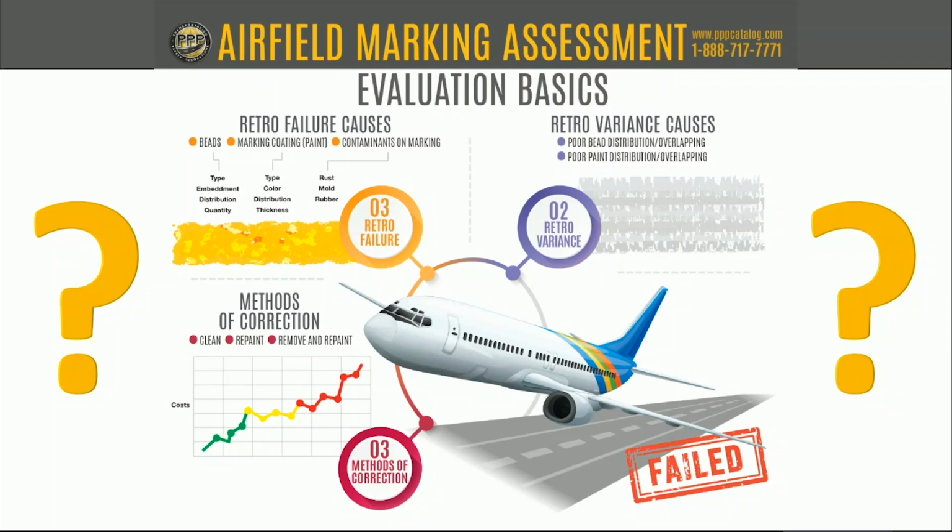In some cases, that means it's made for an 8-inch line. So you have to just make sure you find out what that manufacturer's 4 means. The 17, or the 2 digits behind it, is how big that orifice is. If you're in a walk-behind machine, you're going to be pushing, in a waterborne, you're going to need about a 17 or maybe even a 19.